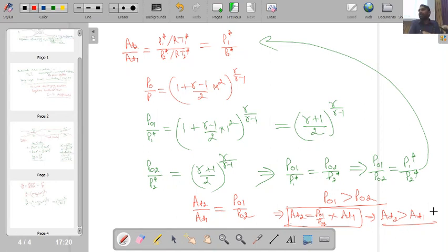And if you are using a convergent divergent section for a diffuser, it will be having a different throat area, and the throat area of the diffuser has to be greater than the nozzle, and this is the ratio of the actual throat area.